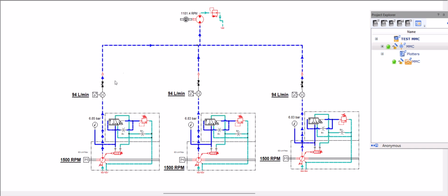right now I have set all the pumps to full capacity by making the resistance 0. As you can see, the full flow and there is no pressure on the pumps. Here, an interesting fact that can be seen is that all of these three pressure compensators 1, 2 and 3 have been set at 280 bar. This is a simulated environment where all three have been set using the knob at 280.